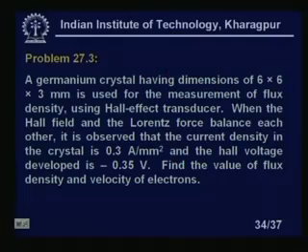Is it clear? That is why I am saying that when I apply a voltage in a Hall effect transducer, which will give me a steady current I, under a steady magnetic field B, there will be a redistribution of the charges, or the electrons, on the two sides of the plate, and the Lorentz force will balance that. Due to these accumulations of the electrons, I am getting a definite non-zero voltage, which we are calling the Hall voltage, right. Let us look at that problem again.